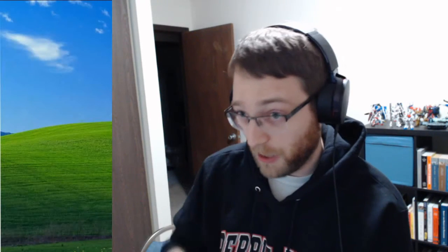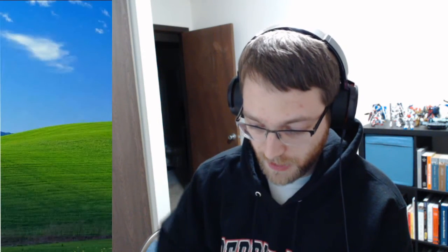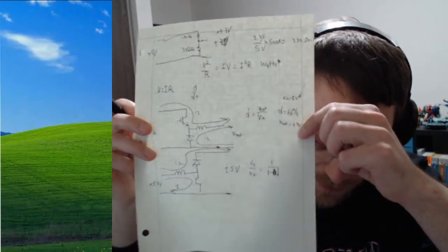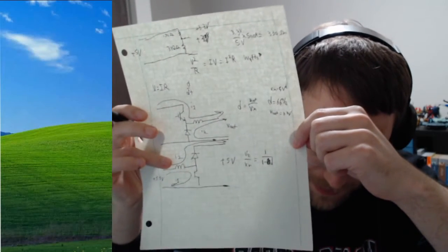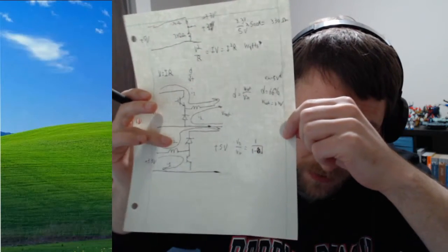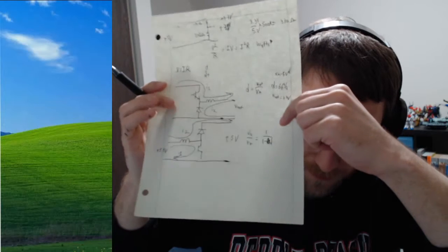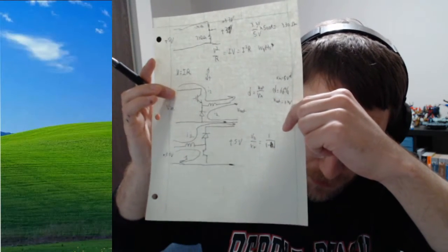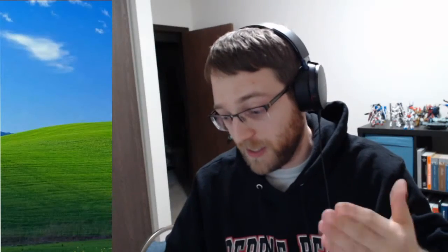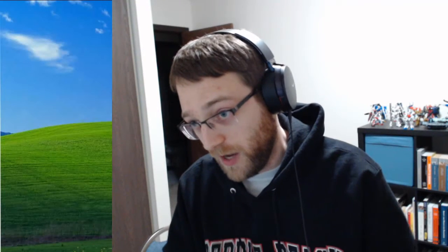The difference between these power electronics and those power transformers is that fundamentally the concept is the same because they're using inductors, but the difference is we have a transistor here that is switching all the time, and this lets us increase and decrease the duty cycle so we can control it depending upon the needs of the circuit. So if the plus 5 volts input line ends up fluctuating, you can still get 3.3 volts out the other side because you have an active component that's switching. With a transformer, you do not have the ability to do that.